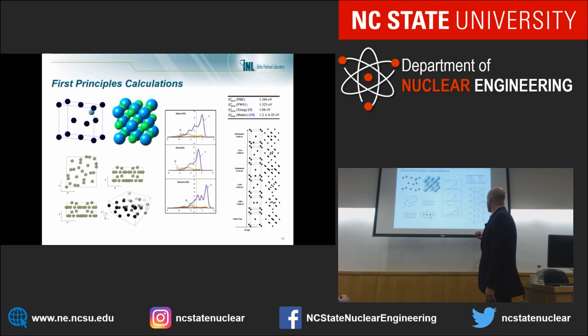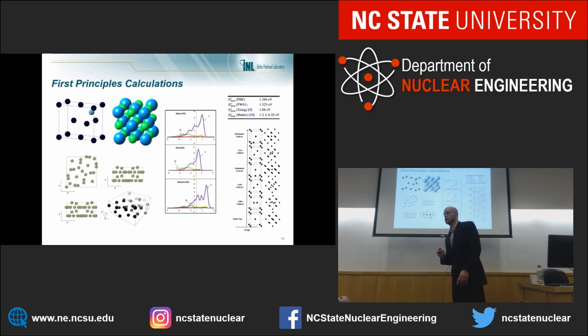And there were still folks who didn't believe these interstitial energies, because if you notice, the interstitial energies are extremely low for metals. They're half of an eV. That's unheard of. That sounds absurd. You would have such a high population of these defects that you're essentially melting the system. That doesn't really make sense.